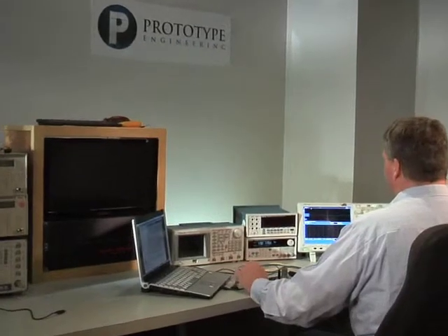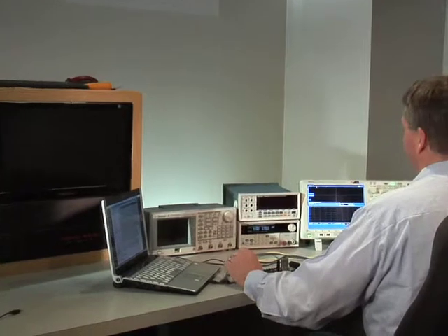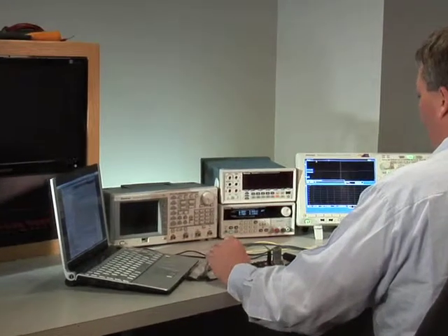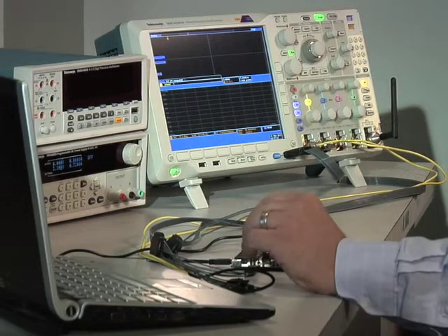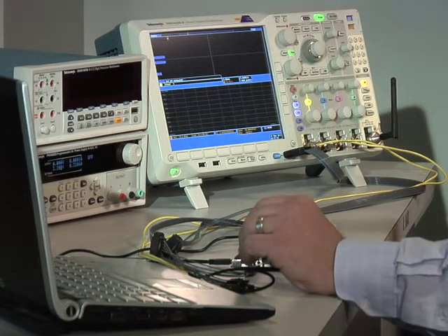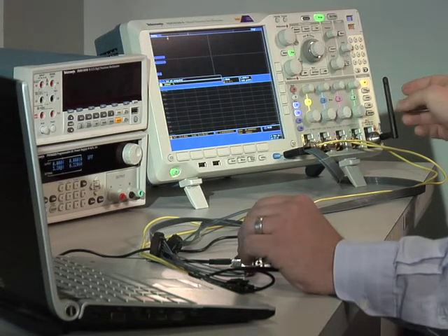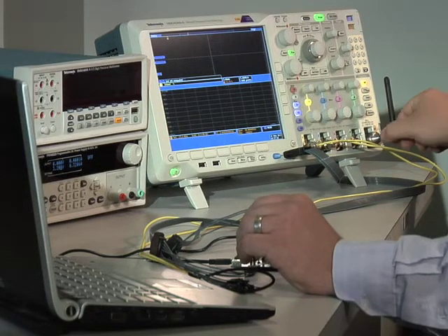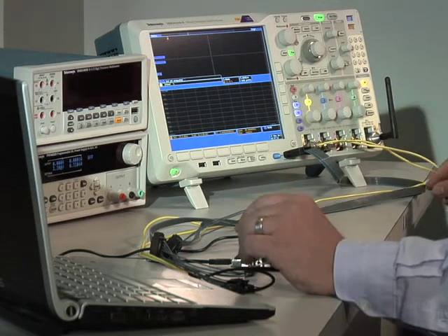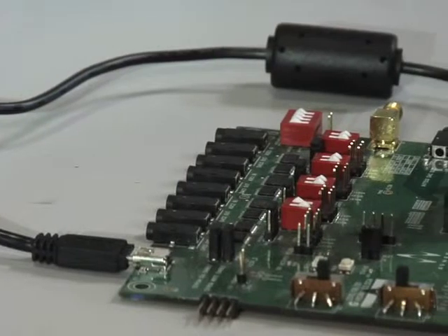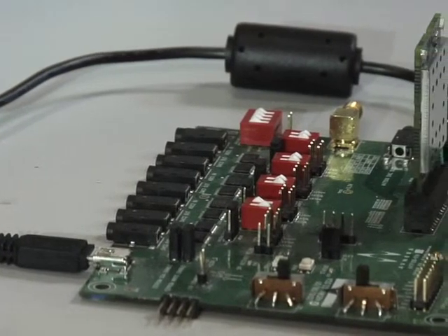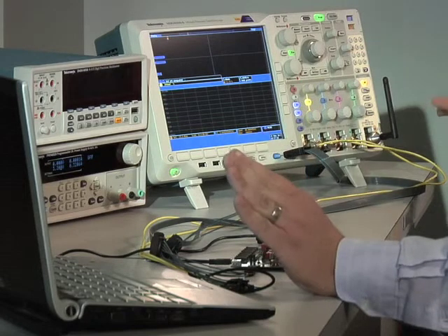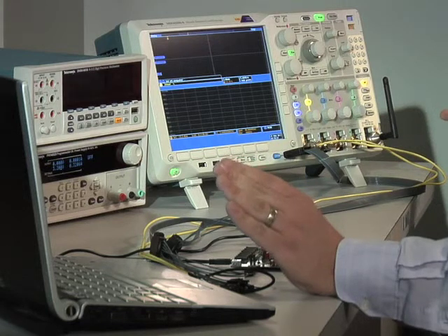So now I've connected the wireless audio evaluation board to my complete bench setup with 2 digital buses, an analog connection, and then the over-the-air RF connection. I'm using an antenna on the front panel of the MDO4000 to receive the signal from the wireless audio system. That way I can see all the nodes in the system. I can also see the entire RF environment, including any interferers or other adverse RF circumstances.